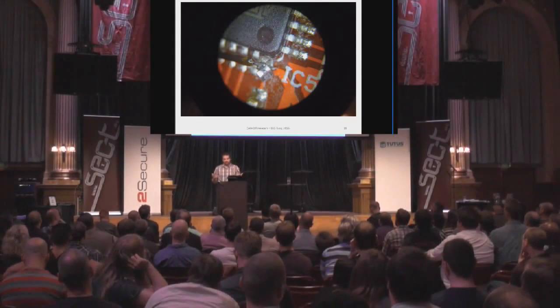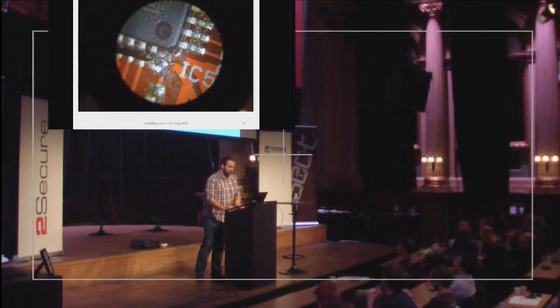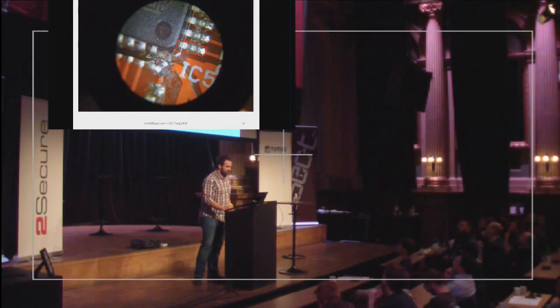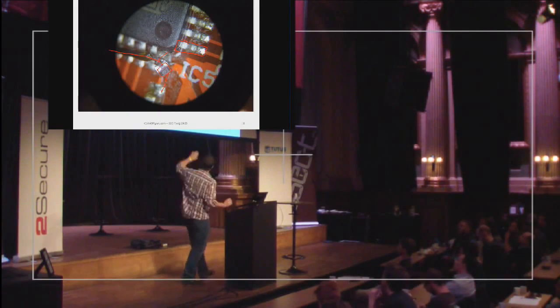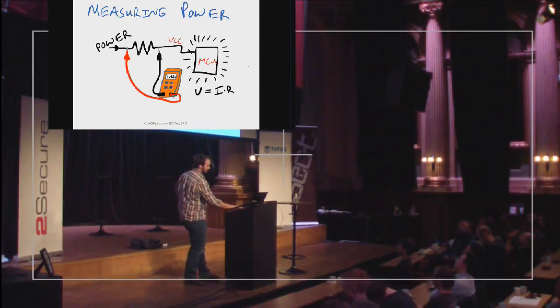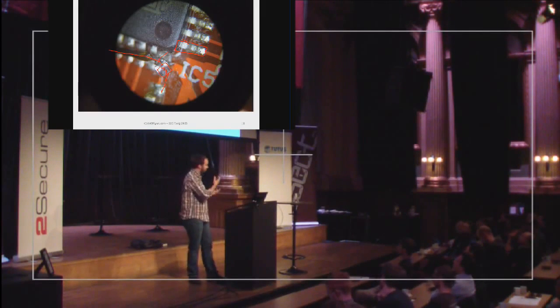And if you have a real board you're attacking, that can actually be not too difficult. This is a view of what's called a TQFP package. This is sort of a top view, so you can see the individual pins here. All I've done is lift one up and insert a very small resistor into it. Over here, there's a wire going off, and it otherwise goes to the rest of the power plane. This is exactly like the diagram I just showed. We're able to achieve this power measurement on a real board with a fairly simple modification.